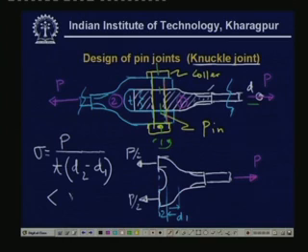to satisfy this expression, that is P allowable divided by T times D2 minus D1. This is the normal stress, it should be less than sigma allowable. So this condition has to be satisfied. Now once we know that, then we can design what is the value of D1 or D2 if T is properly chosen. So this is one way of failure, and we have one expression here.